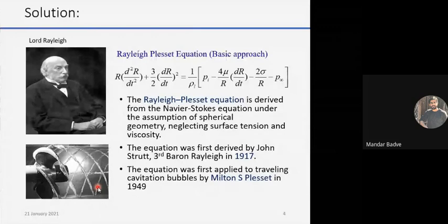So what you can imagine is, imagine this is a propeller, which is attached to, let's say, a ship, right? What the propeller basically does is it pushes the liquid in this direction, which drives the ship in the opposite direction, right? So it increases the velocity of the liquid in this direction. But when the velocity of the liquid in this region increases, we all have studied Bernoulli's theorem in our 11th, 12th, and even engineering. So when velocity increases, the pressure reduces, right?